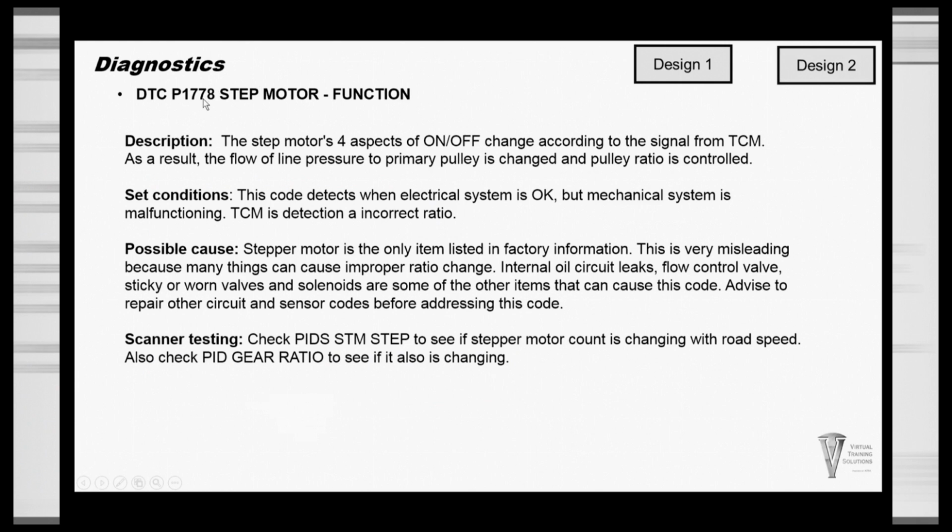1778, this is the most common code. Everybody sees this and goes, oh no, it's a stepper motor. Replace the valve body. Change the valve body or the stepper motor. Oh, it didn't fix it. Okay, now what do we do? This is stepper motor function.